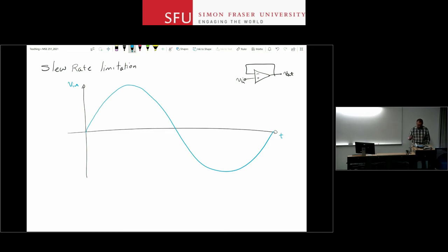And you connect it, you're saying, my signal is, let's say, a 1 kilohertz signal. The omega t of my op-amp is, let's say, 1 megahertz times 2 pi. So I shouldn't have any speed limitations here. My op-amp should be able to amplify signals all the way to maybe around a megahertz if I'm applying a 1 kilohertz signal here. So let's go and use it. And then you hook it up to your speaker, and all of a sudden your ears, very sensitive to distortion, hear a lot of unpleasant sounds.